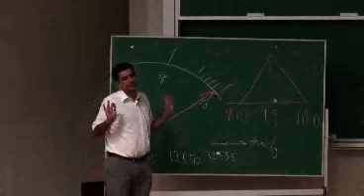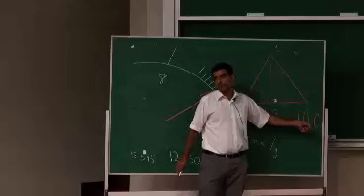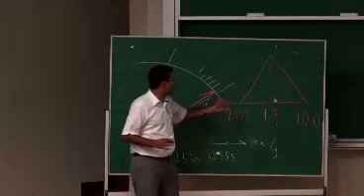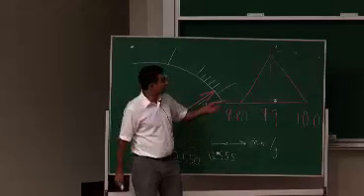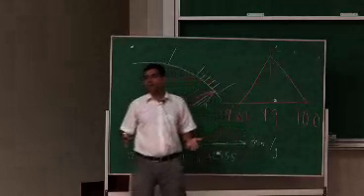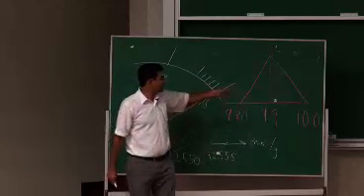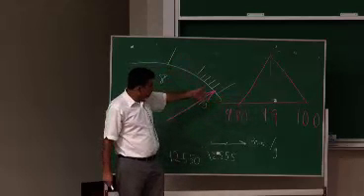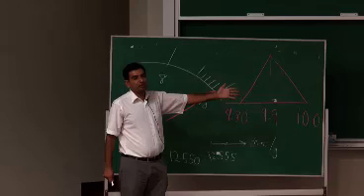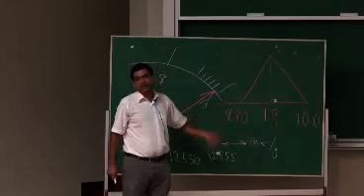Okay, I am slightly conservative, so I will put this at 9.80 here and 10.0 here. So I know that my true measurement cannot go beyond these extremities. So now I take this half length, which is 0.1, divide this by under root 6. This will give me a standard uncertainty. So I will associate this measurement with a triangular probability distribution, 68% confidence, and an interval and an uncertainty of 0.1 divided by under root 6.